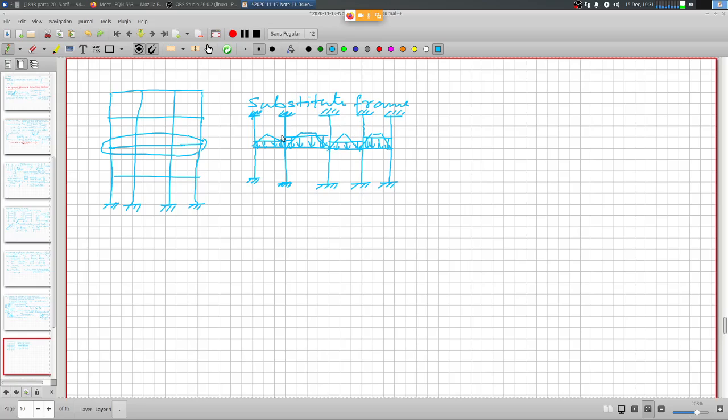The only issue is, what is the critical condition? If all the spans are loaded, and obviously this is continuously cast, so it is a continuous monolithic construction, then there are going to be issues here with respect to the loading pattern. If these alternate spans are loaded, then there will be some kind of bending moment distribution. If all the spans are loaded, then there will be another sort of bending moment distribution, and so on, right?